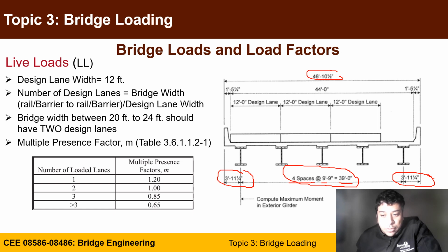However, the width of the drive is different because you will have a barrier to ensure safety. So you will have a width of barrier where the loading can start for the live load. Here we are talking about design trucks. Let's say you have a barrier from this side and a barrier from this side.